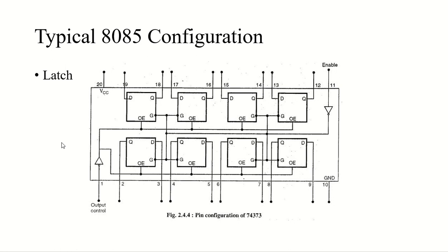So here in the image you can see the chip, that 8-bit register features totem pole tri-state output that are designed for capacitive or low impedance loads. The 8 latches are D-type latches, which indicates that when enable is high, enable is basically this G switch, the Q outputs will follow the D input, and when enable is low, the output will be latched at the level of the data that was set up. Okay, so it's a bit confusing, so I'm repeating it one more time.